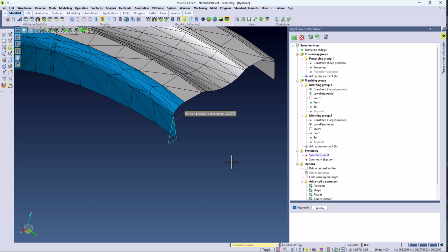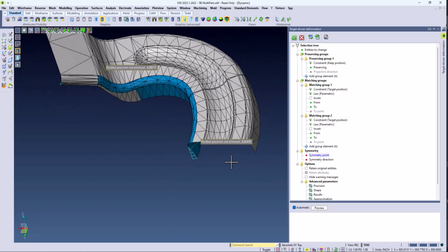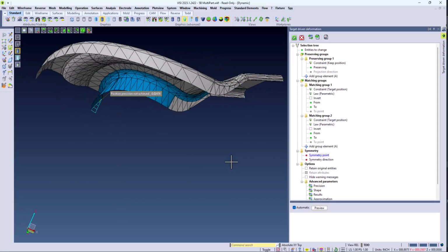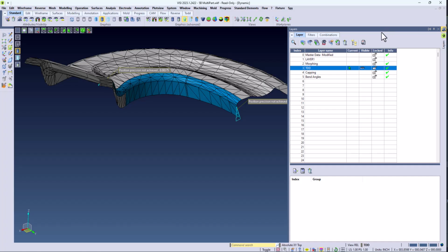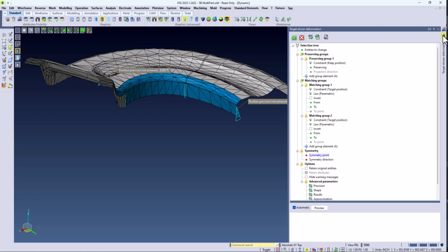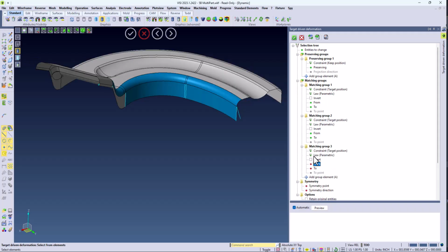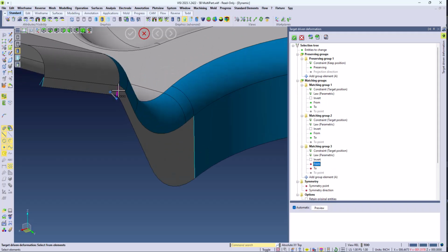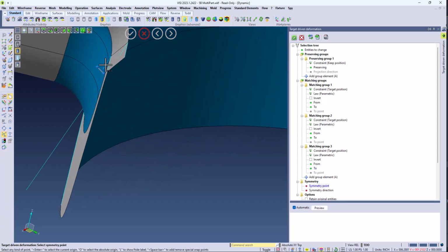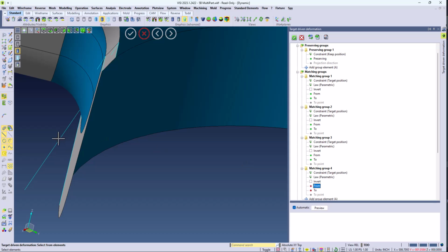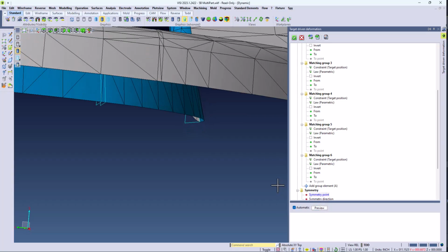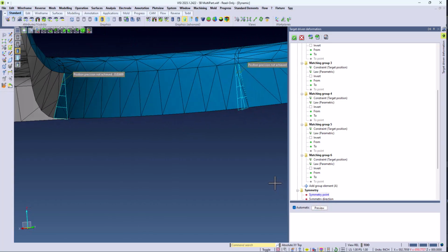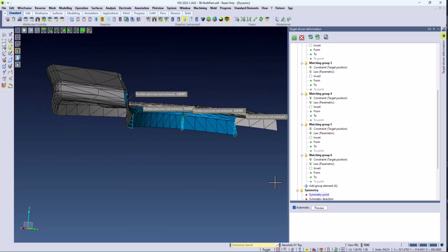Now, we're only morphing from these sides, but we can also add some additional geometry to this as well. So I've already drawn some stuff out here, so you can see where these edges are right in the middle. We can add more constraining wireframe to be able to have a more accurate reading within Target Driven Deformation. So I'm just going to add some more constraints to and from. And then basically repeat this across the entire area. So I just add a few others. And as soon as I have everything selected, now I have additional constraining areas to more accurately show this 20-degree bend.